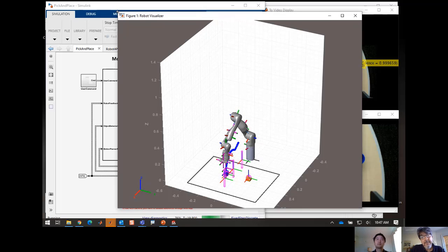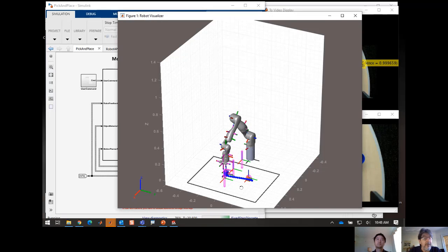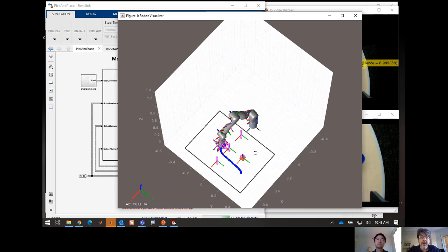Correct. Not just that, by the way. We have the two objects on the platform, but those little purple tubes you see are actual obstacles. If you notice, the trajectory generation is not just a point-to-point connection. It is figuring out a path that avoids the obstacles, going from the point where we pick the cup to the particular drop-off location. And avoids the obstacles, correct.